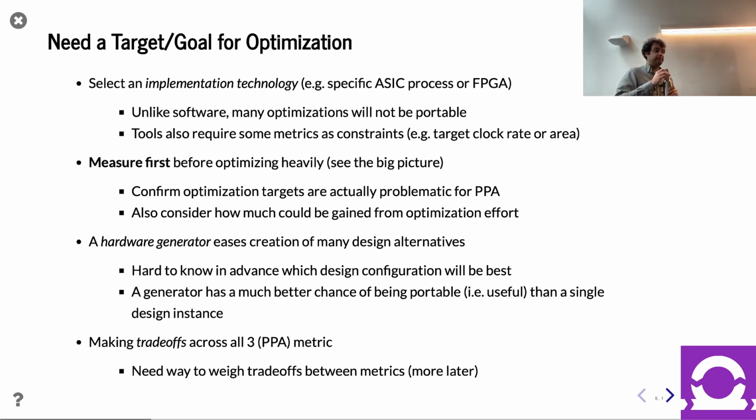The floating point unit in the TPU? So okay, I'm not sure I fully understand the question, so please correct me if I get it wrong. Within AI hardware accelerators in a broader picture, a common way to optimize is to use fewer bits, right? If you can use fewer bits, that's less hardware. It's a great question for explaining today's topic, so I'm happy you asked this. If you use fewer bits, that's less hardware, less cost, also less power. Or alternatively, for the same amount of hardware, you can get more numbers, perhaps giving you more performance.